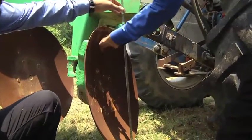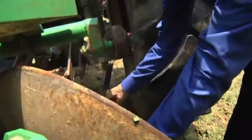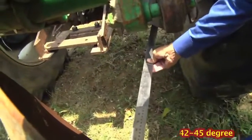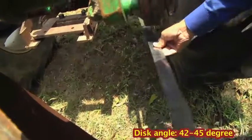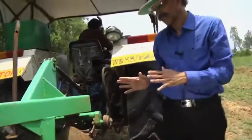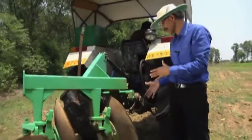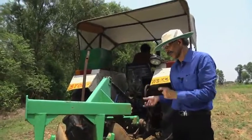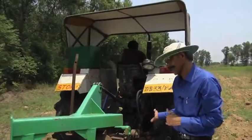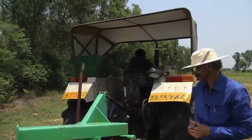So, we can change this, and the disc angle is, now this is the direction of travel. With the direction of travel, if you take the disc, the angle which we maintain is what we call the disc angle. Now, both the disc angle and tilt angle are very important. The tilt angle generally varies between about 15 to 25 degrees or so, and the disc angle varies between 42 to 45 degrees with respect to the line of travel. These are very important when we want the total output of these discs.